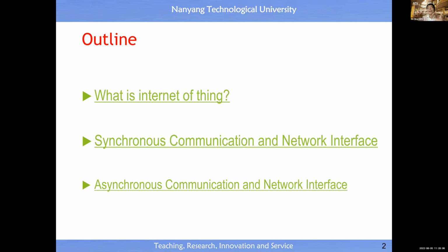So then we need to synchronize byte-by-byte communication. The first universal method is to make use of hardware. We have a dedicated signal line to indicate: this is a time window for communication of 1 byte or a series of bytes. That's it. Then this method has a drawback because it's costly.